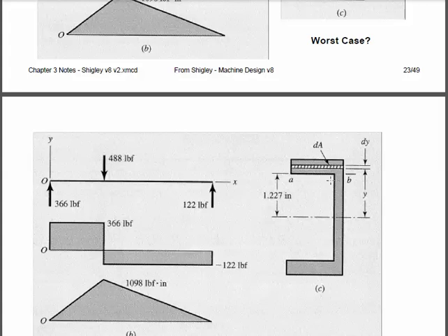Now, why would we have low shear stress right below that cut line? Because Q would still be very large, but this quantity called B, which is the thickness across the section here, sorry, our largest shear stress would actually be in the thin section right below the cut. Because that B is small, that would make that shear stress large. Shear stresses in this section aren't too bad, but right below the cut, our shear stress is going to be very bad, because Q is going to be large, but B is going to be smaller, dividing by B.